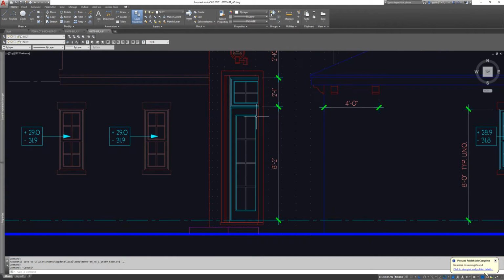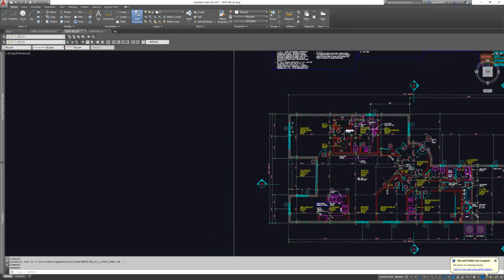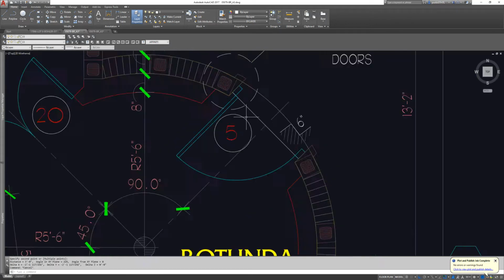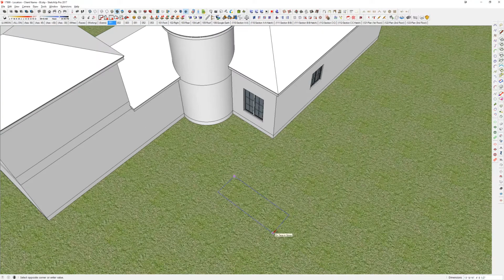The tower actually has a door. So I'm not going to open my doors right now, but I know it's an 8-foot with a 2-foot transom, and it should be a 3-foot door. Yeah, so it's a 3-foot door. So really, I'm going to create what I have talked about previously as my cutting block. My door is going to be a 3-foot door, so I know it's going to be 3 foot 4 inches because I have 2-inch buck on either side.